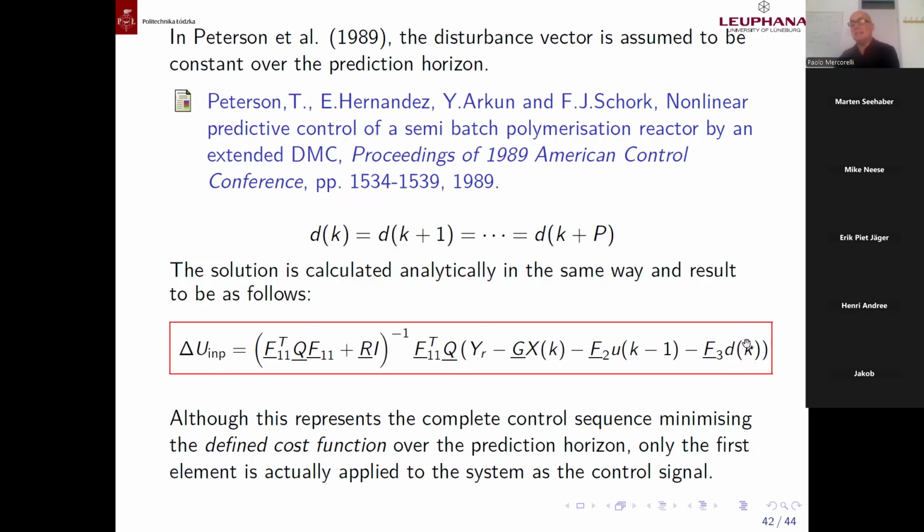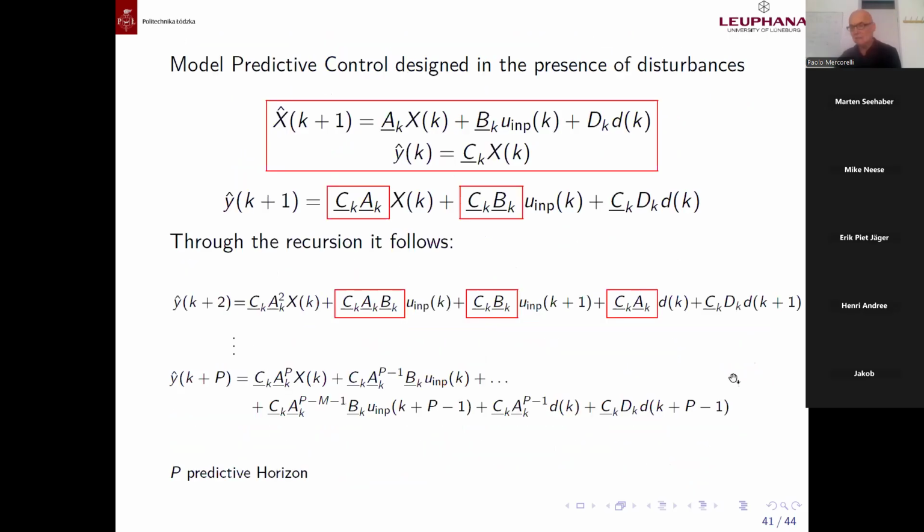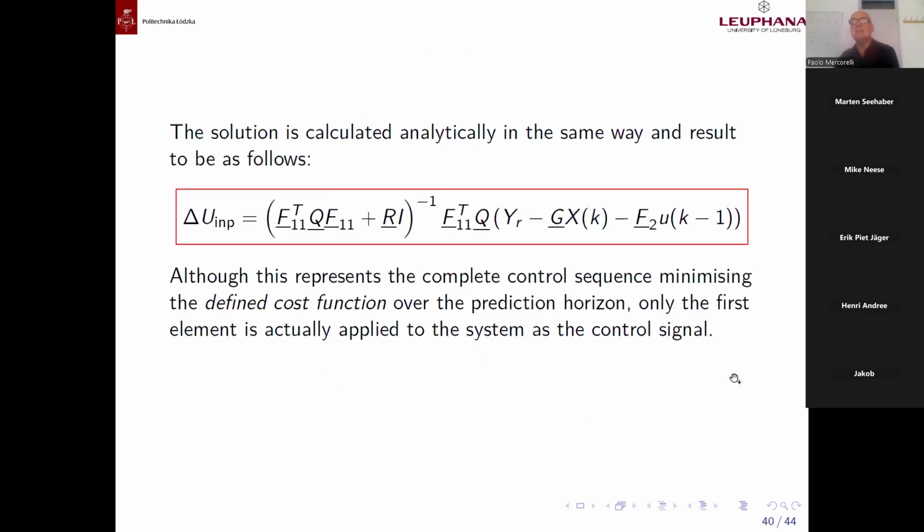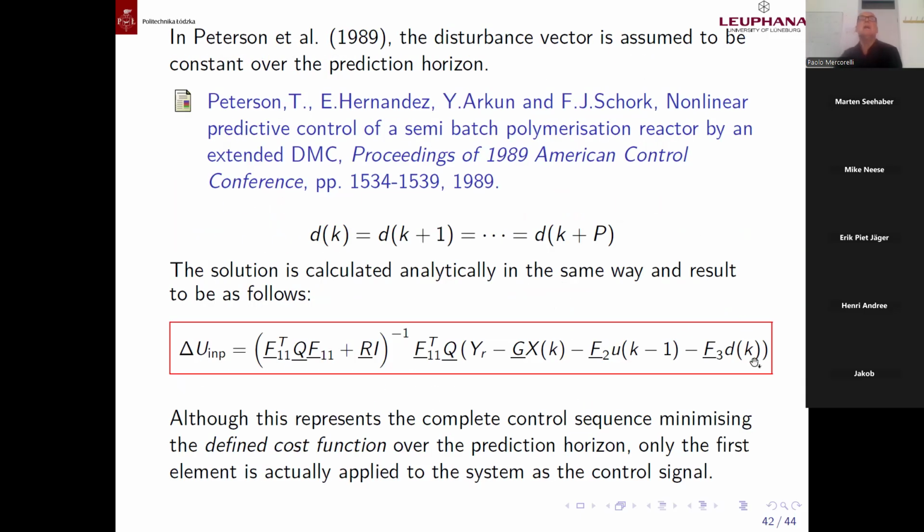But even though it's not estimated, we can nevertheless use this scheme here, or the first one, without the past value, to compensate, not exactly, or not so well as this one, because it is impossible to know the disturbance perfectly, because it's an external signal. It can be estimated, but estimated means estimated. We cannot know exactly what it is. Nevertheless, this procedure allows a good compensation. Of course, with the assumption this is constant.